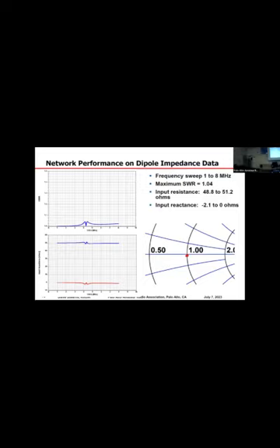So this is the whole point. I'm fixing the feed point to look like a pure resistor, flat at all frequencies. This has nothing to do with what's going on in the fields in space. It has nothing to do with the Q of the antenna, but it will have a lot to do with the Q of those formulas. So this is why we're going to make an antenna that has an apparent Q of 0, not an actual Q of 0.